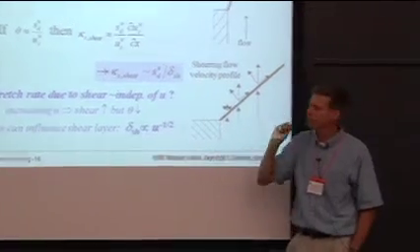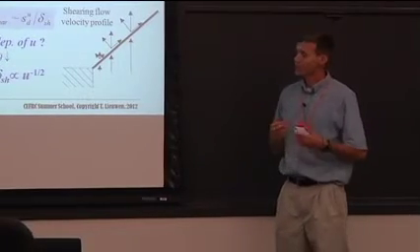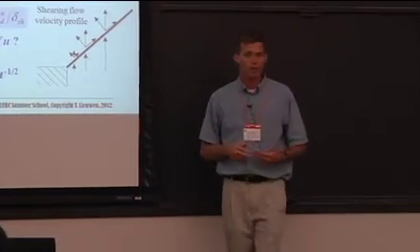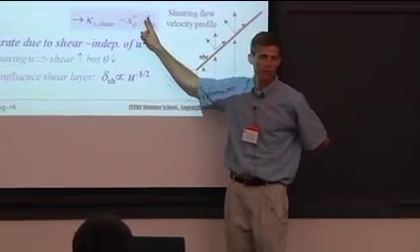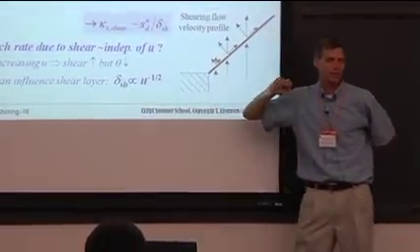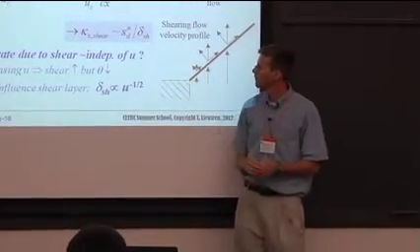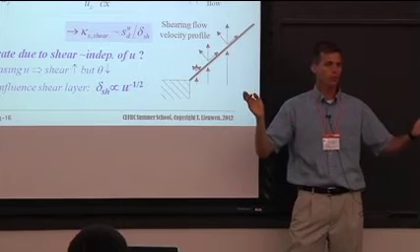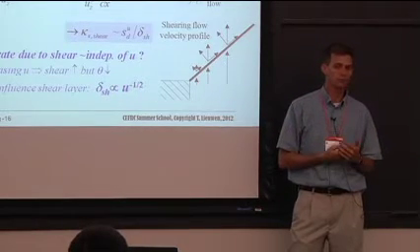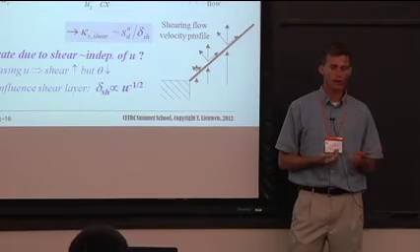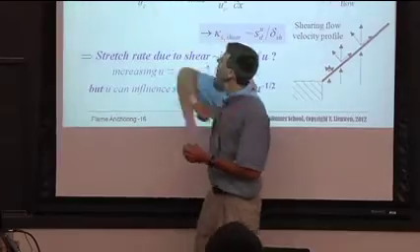So what does it tell you? It tells you that the characteristic velocity scale for shear strain is not the flow velocity, but the flame speed. Another question you might ask is, well, where is the flow velocity in here? There's no flow velocity. So what this is telling you is that if somehow you can fix your shear layer thickness, delta, doubling, tripling, quadrupling your flow velocity has no impact whatsoever on flame stretch. And why is that? Well, it's because of the canceling effect of theta and du by dx.